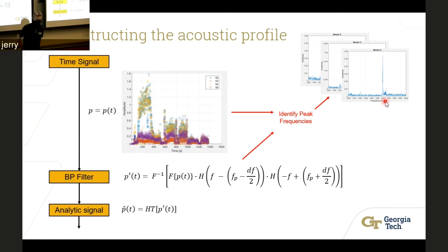Okay. Yes. So that was one of the biggest aspects of the beginning of this project. The bandpass filter that we apply here was an extremely sensitive step. Our bandpass frequency, so this delta F, basically the frequency that we're bandpass filtering, we had this at like 5 different frequencies, and it took us about a couple weeks to find the right range of frequencies that would result in our modes not changing that much.